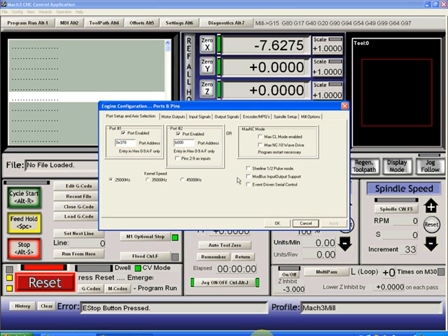Over here on this side, you do have the choice of setting up a MaxCL or a MaxNC. If you do this, you don't need to set the pinouts for the motors. But these are only applicable to the Max series. Leave them off otherwise. If you have a Sureline, select the half pulse mode. This stretches the mode specifically for Sureline products. Most do not need it and don't use it unless you have a Sureline.